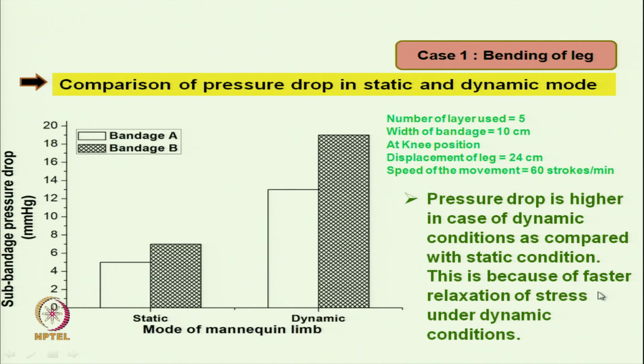This is because of the faster relaxation of stress under dynamic condition. If it is in dynamic condition, stress relaxation will take place at a faster rate, and even structural reorientation will also be there. So, that will also take part in stress relaxation.